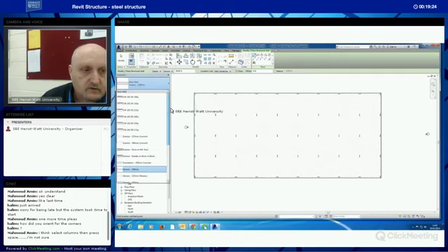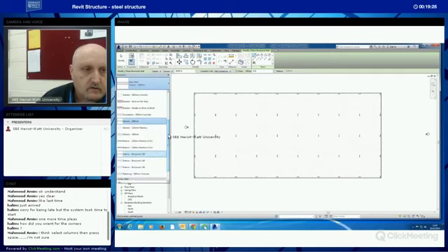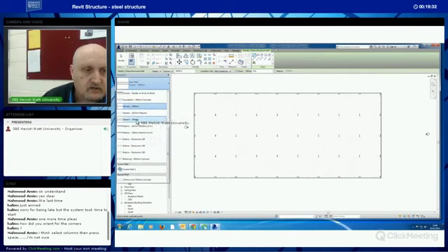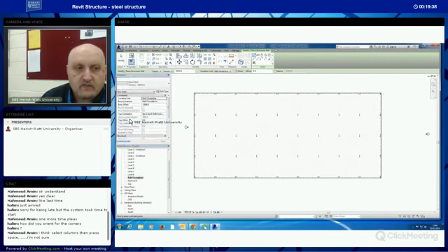I spoke too soon. No partition. I'm just going to go with a generic wall. I think this one I'll have to do. I'll have to change its properties at a later date. I'm going to select that wall. I want to make sure that it's finish face exterior,